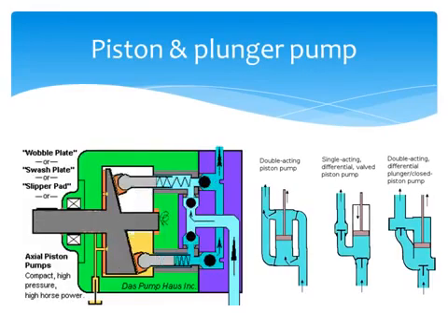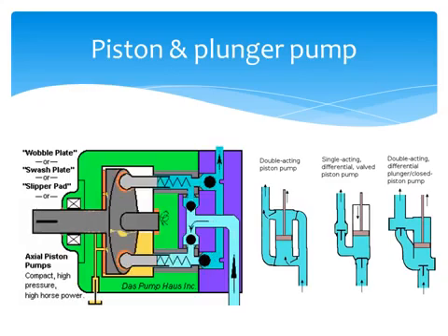An axial piston pump has a number of pistons, usually an odd number, arranged in a circular array within a housing, which is commonly referred to as a cylinder block, rotor or barrel. This cylinder block is driven to rotate about its axis of symmetry by an integral shaft that is, more or less, aligned with the pumping pistons, usually parallel but not necessarily.